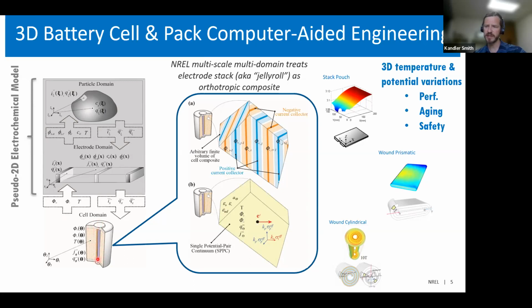So there's heat generated within the cell as it's charging and discharging, and of course, you're cooling at the surface. And so there's generally going to be a hotter region in the center of the cell. That hotter region makes the kinetics and diffusion processes faster, and so you end up preferentially using that part of the cell during charge-discharge processes. This isn't an issue when you've got really small cells, but when you scale up to huge cells, such as lithium ion for stationary storage these days, I know there are 250 amp hour LFP cells, and they can have huge temperature gradients if you start to cycle them above perhaps a C/2 or a 1C rate.